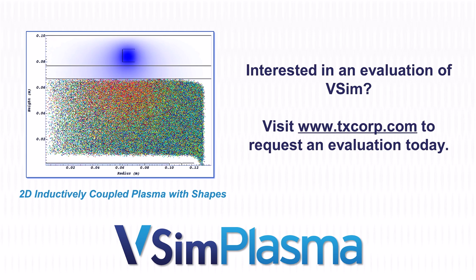The very first question I have is, can the plasma generation converge in 2 RF periods? Thank you for your question. The convergence of a plasma is very particular to the initialization. 2 RF periods is pretty short for a low temperature plasma. Realistically, you wouldn't be able to reach an equilibrium in the plasma generation over that time period. But as you can see from our simulation here, you can start from a uniform plasma and form sheaths within that time scale. So yeah, next question.